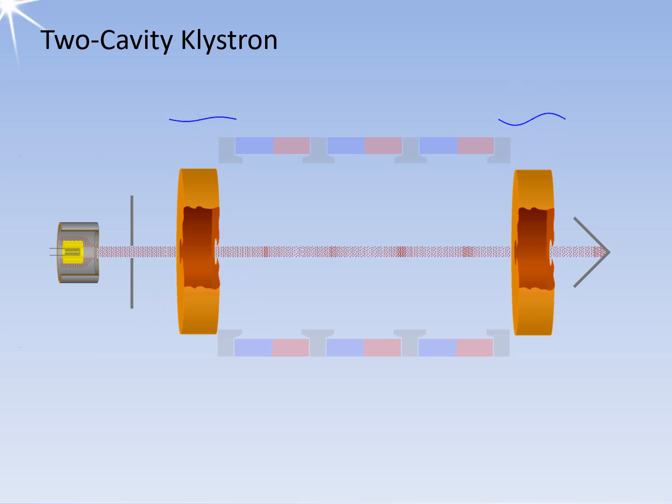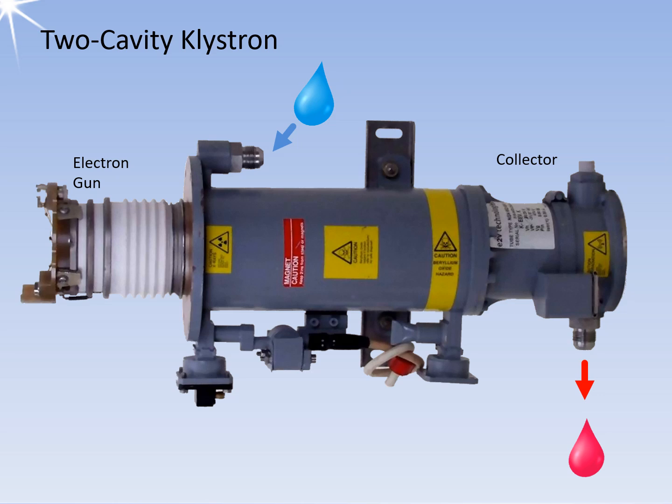Nevertheless, these electrons still have enough energy behind the amplifier resonator, so the collector that catches them must be well cooled. This cooling can be done either by a forced airstream or by a cooling liquid. The two-cavity klystron is an amplifier tube used primarily in military radar sets.